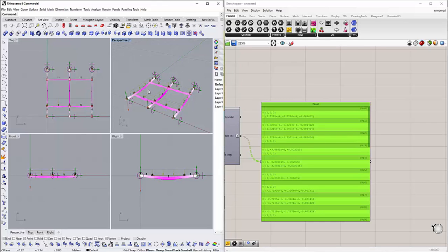So 1 and 7 displacement will be the same. So if you see this and this values, that is this mullion 1 and mullion 3. So for that we need to go in this line and this line. So here you can see the value of displacements are same for both the mullions, while the center mullion 4 will show more deflection. So that value is here for the center 4 mullion.